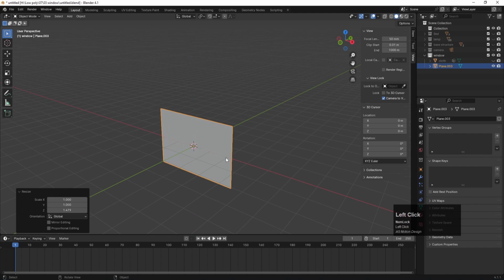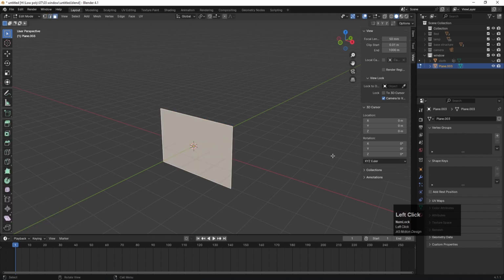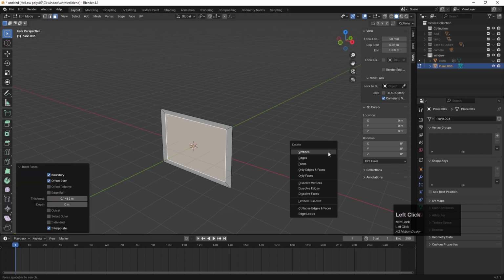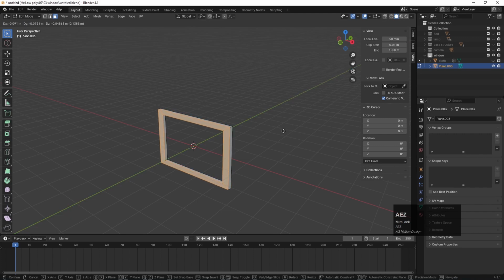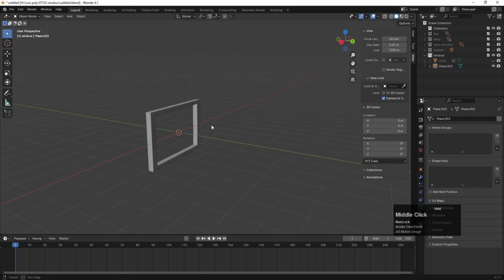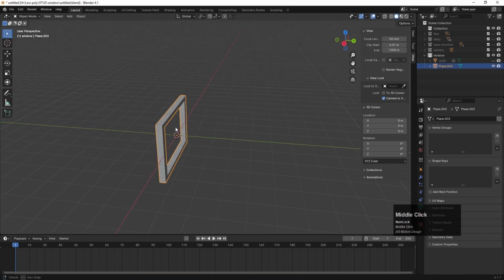Okay, go to the edit mode, select this and press I for inner extrude like this. Then simply hit delete and choose faces like that. Then hit A, then hit E for extrude, then extrude this on Z axis somewhere around like this. Okay, not Z axis but Y axis somewhere around like this. Okay, go to the tab view, we will get this kind of extrude over here.